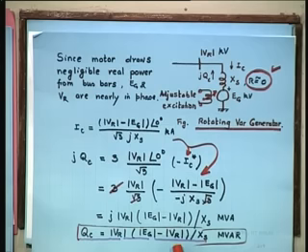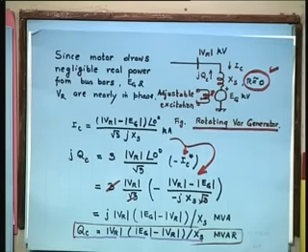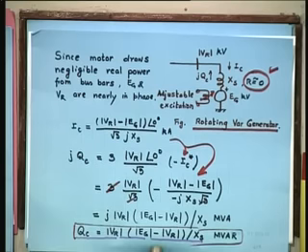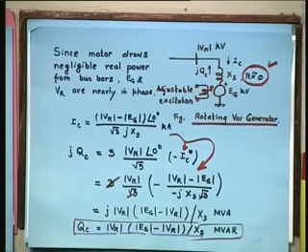And notice the change from this equation to the static VAR system equation. There it was second order, the voltage was second order, here it is first order. Can you tell me one more reason why dynamic compensator is better than static compensator? Because if you recall, there when the voltage sags, you need the help more, and at that time help is less, because it is squared, second order effect. Here what happens, if VR sags, this goes down, but this goes up. So, there is a counterbalance, something goes down, something goes up. So, QC remains a fairly good value, it will not reduce drastically, which happens in the static VAR case.